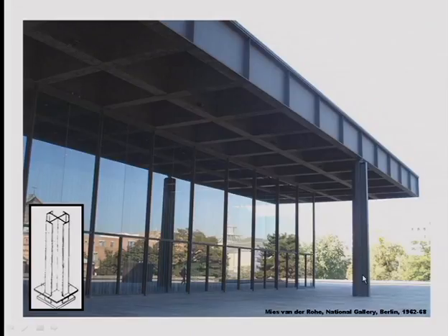This column, which is slightly tapered, is like a white flange, but like 4 white flanges welded together, separated and re-welded together. So it's a custom made piece that takes advantage of the standards, but makes a new profile. And you also try to taper it, because of course you won't need the same amount of material towards the top. So this is the key.